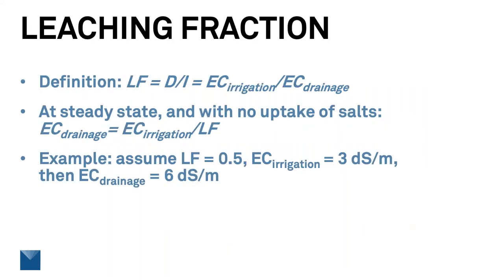Well, if we know the irrigation amounts, the substrate water content, and the field capacity, we can classify shots as recharge or as drainage. By adding up the drainage shots for a day, we get the D value for the water balance equation. If we divide the daily drainage by the daily irrigation, we get what's called the leaching fraction. And you can see that equation on the top here.